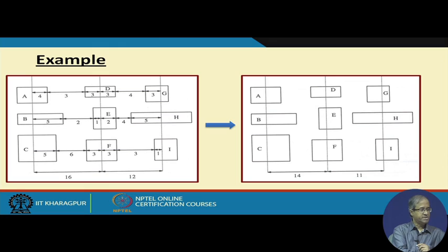So, this is exactly what we do in this kind of virtual grid based compaction, where, given a complete layout, which I am repeating, you imagine grid lines, and as and when required, you align the small rectangles to the nearest grid, then let the grids move with all the attached blocks or objects with it. So, this is how you are doing the compaction. Here the checking for the design rule is also simple. And of course, this algorithm will be linear in the number of blocks. So, the time complexity will not be very high, all right. So, this is the method.